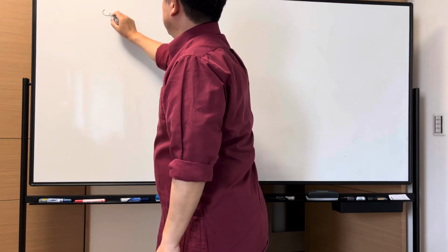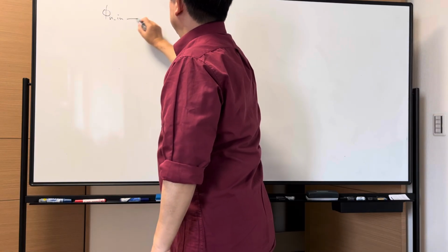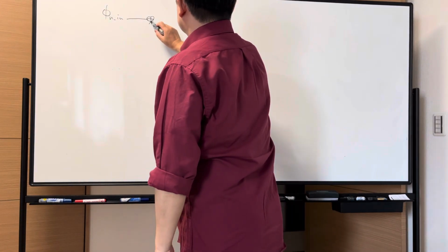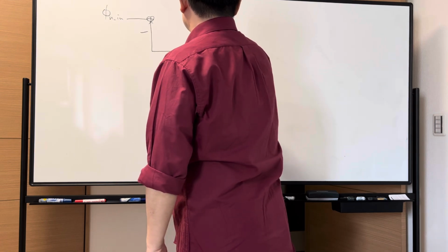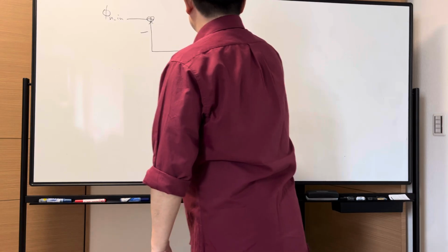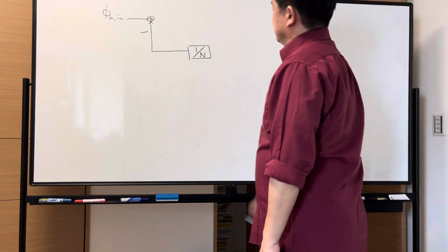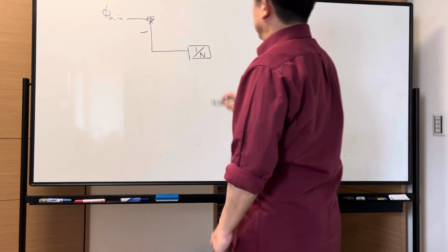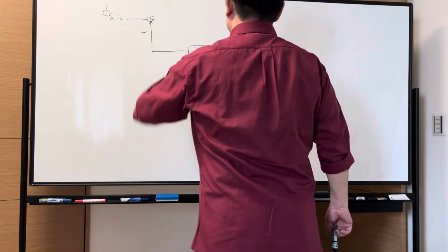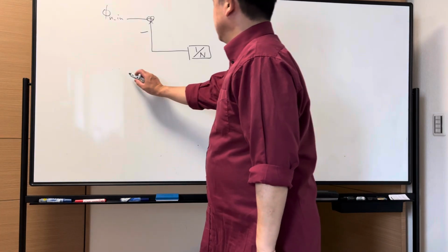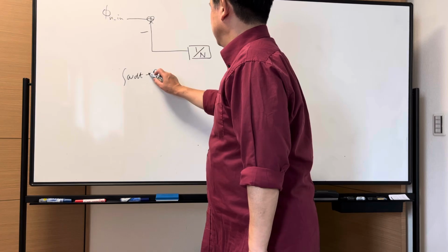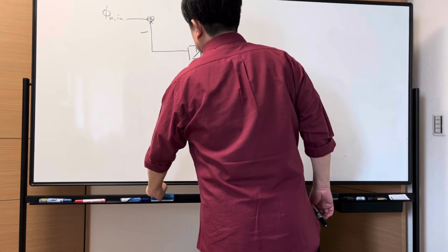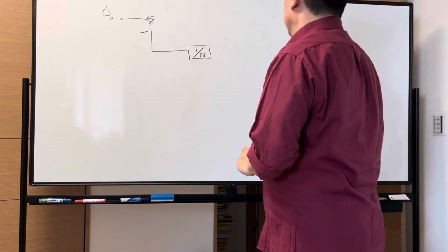There's a PLL, a piece of noise is applied from the clock and the PFD, with the divider also included. For simplicity, negative feedback by the divider function has transfer function 1 over S and 1 over N, because the angular frequency omega is divided by N, which makes the feedback omega very small. But omega is integrated to phase, so the linearity lets us talk about the phase, and we can apply this feedback gain also.